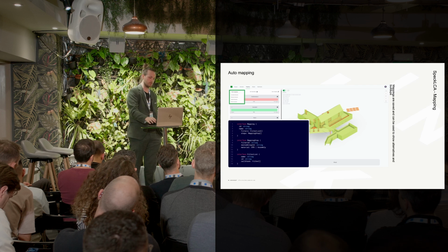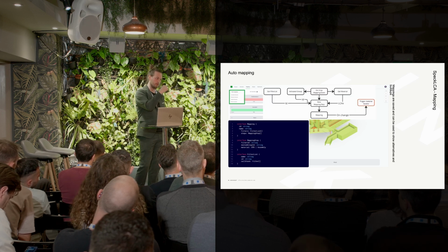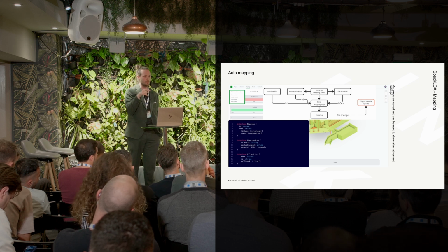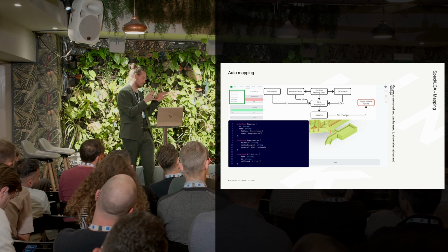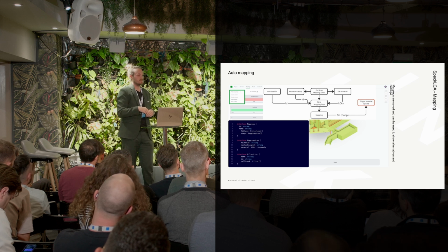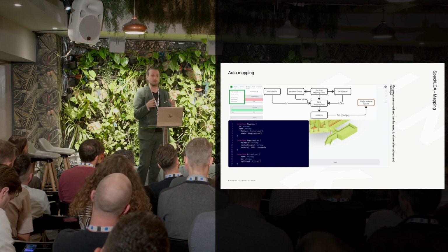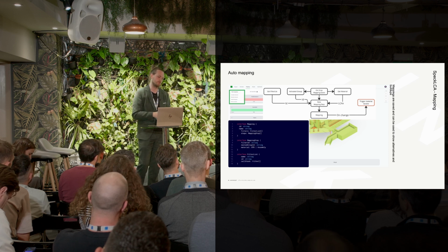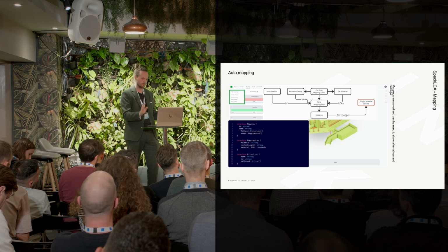So we're adding them by logic instead. Every time you're mapping a material, it's checking what filter you have currently. It's checking what material you're dropping on what group, and then it's remaking that. So if you ever had a filter that sorts everything on, let's say, brown colors for early phase Rhino stuff, then that's wood. Then you load another Rhino model that has the same color scheme, because that's your BIM standard or your Rhino standard, and it auto-maps it. You don't have to redo it again. So that's the main thought. You map once, and then you're done.